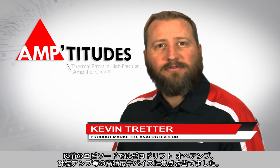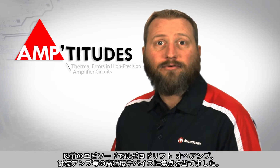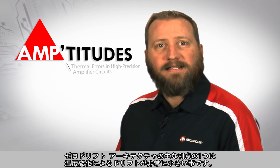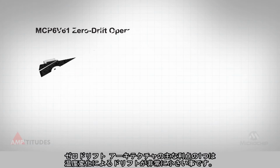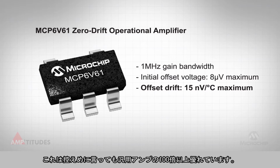In past episodes, we focused a lot of attention on precision devices, such as zero-drift op-amps and instrumentation amplifiers. One of the key benefits of the zero-drift architecture is extremely low drift over temperature. For example, the MCP6V61 zero-drift op-amp specifies a maximum drift of 15 nanovolts per degree C, which is over 100 times better than that of a general-purpose amplifier, and that's being conservative.